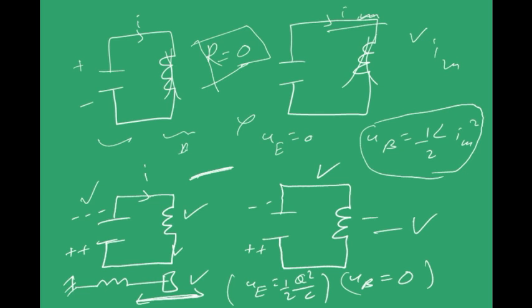But what happens in practical case? The wire with which the inductor is made and all these circuits are made, that wire has some resistance. So through that resistance, energy is dissipated, and slowly all the energy is spent away and oscillations die or they're damped. Now you may ask me, is it possible to maintain these oscillations if I build a circuit with really zero resistance?